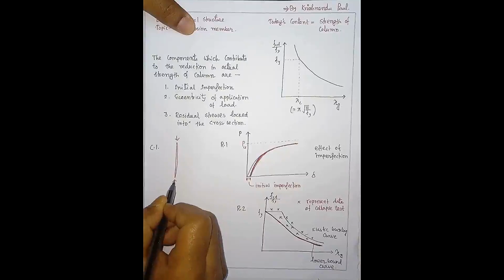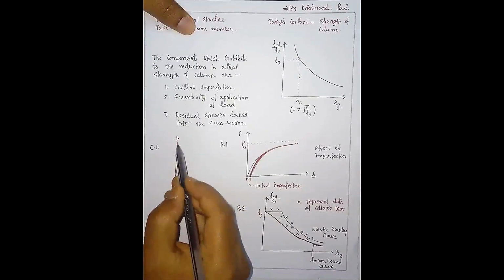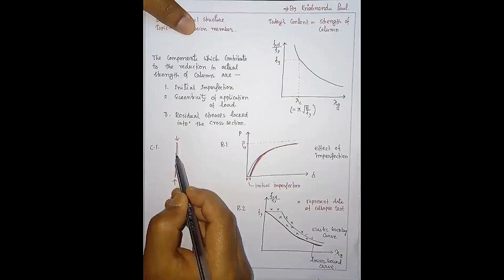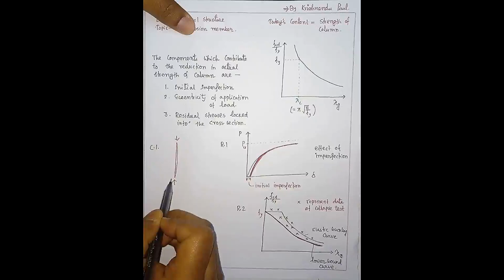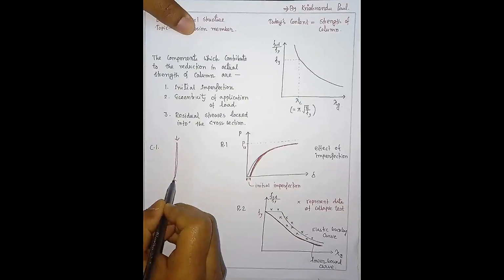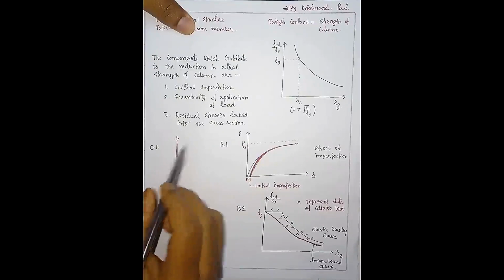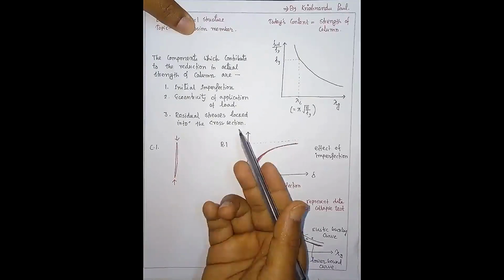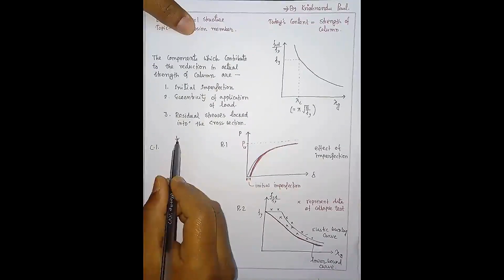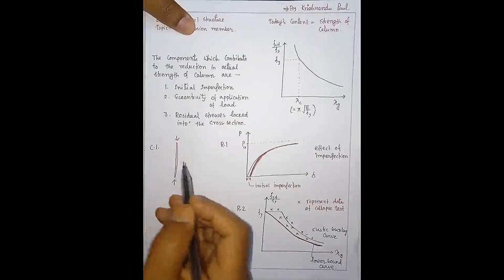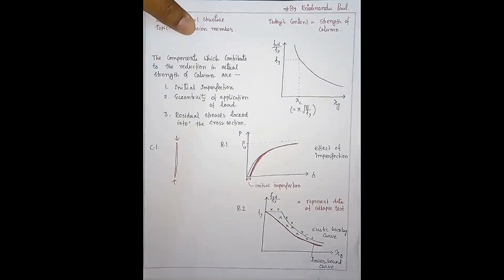Now if we use this column at our site, what will happen? The load is passing through the line on the left, and the member line is the right one, so this imperfection will create some eccentricity in the member. So at the very beginning it will be subjected to a bending moment.